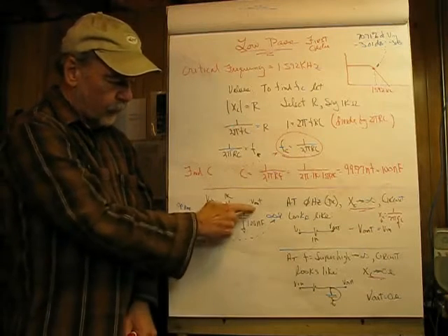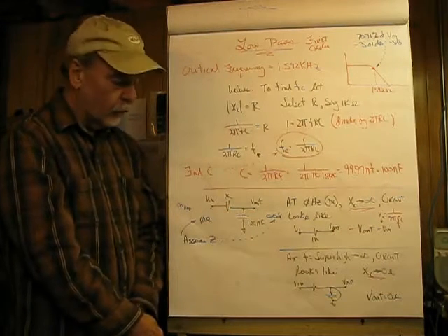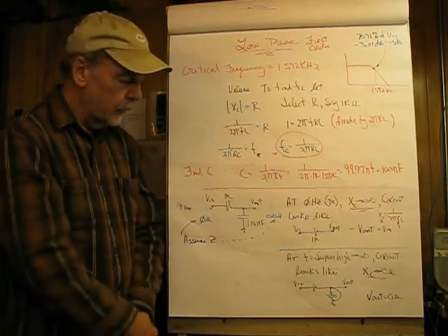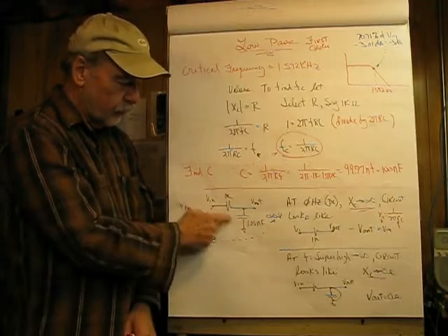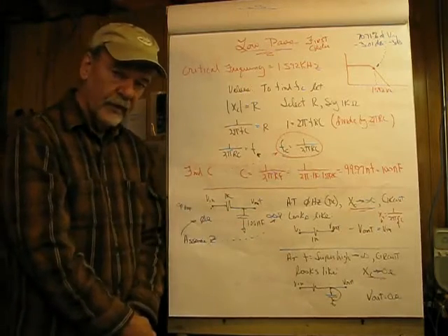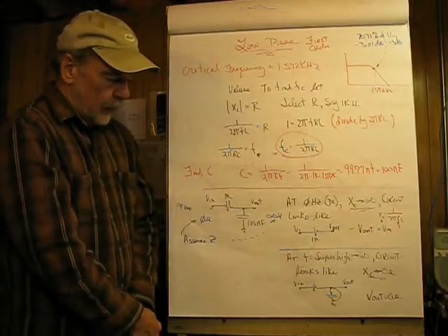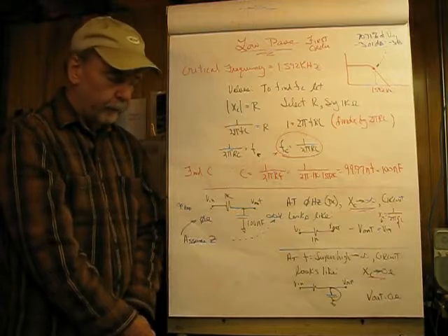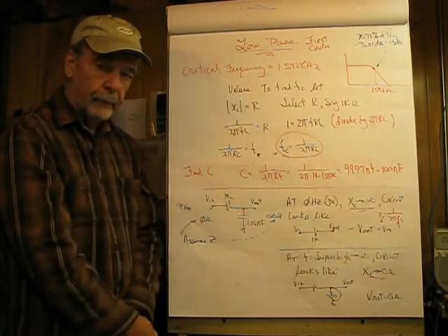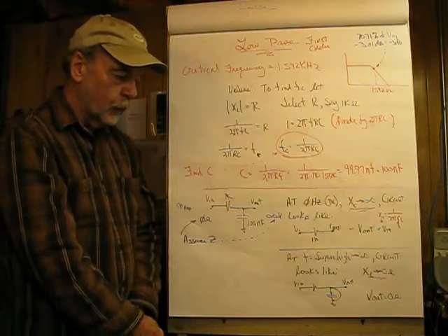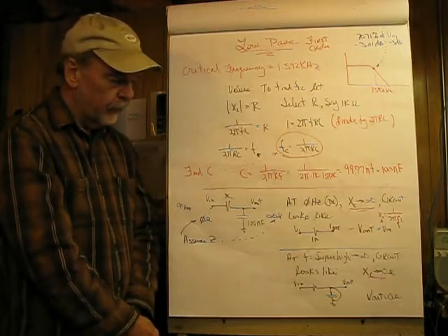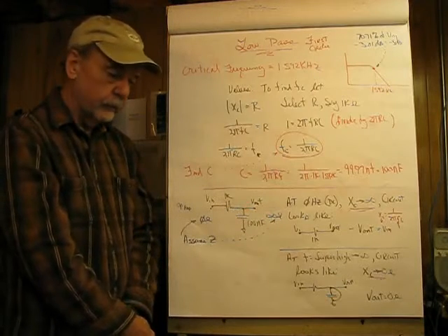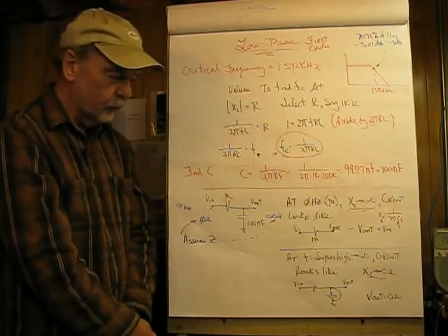And the second thing is we look at V out here is unloaded. So put a meter out here, that's fine, it's a megohm, but whatever. It's not going to hurt anything because these impedance values are relatively low compared to the loading. And theoretically our load would be infinite. Now if we're coupling this into an op-amp in the non-inverting mode, it could be very, very high. We would have to provide a resistor to ground out here for bias currents, but that could be in the hundreds of thousands of ohms.